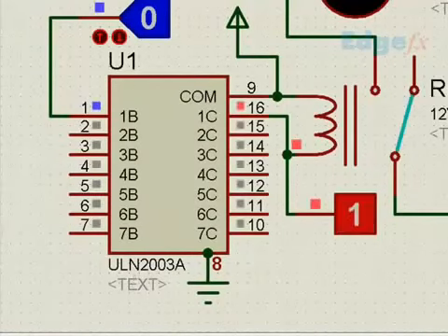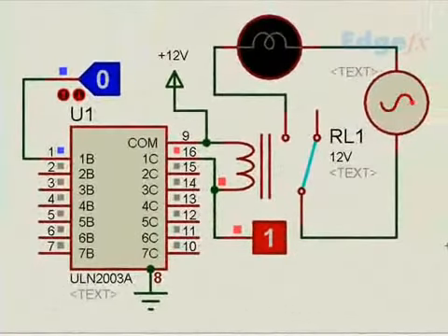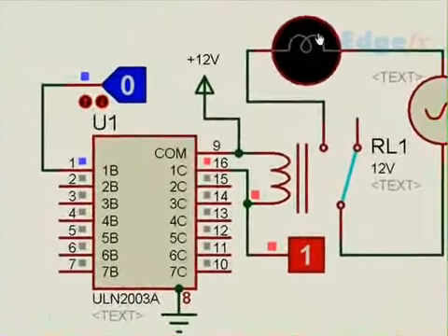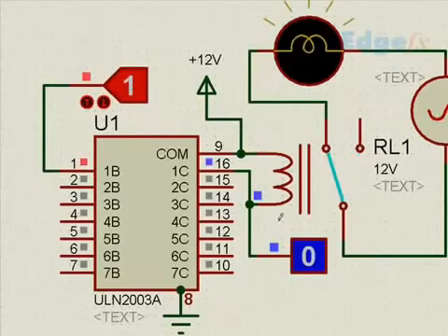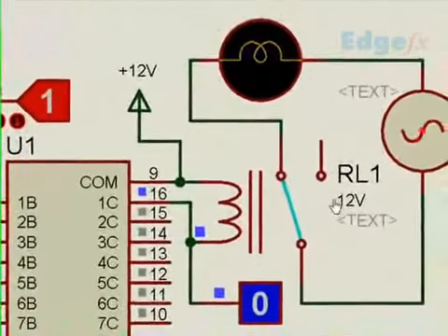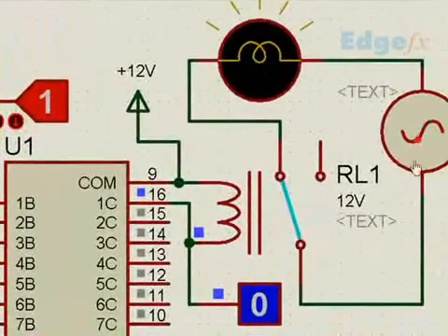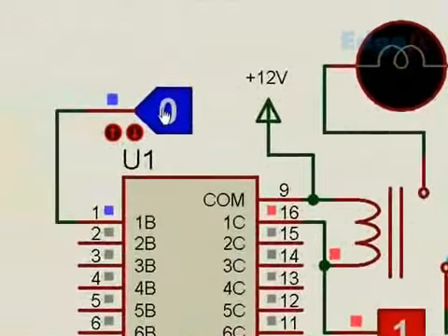Now when we operate this particular system, we find the AC supply is available and this lamp is not glowing. Why? Because this point is high and this point is also high, high being 12 volt, and this point we find in logic is also high. So high to high, the current is not going to flow. Once we make the input high, this goes to 0 and this point changes to this side and the lamp starts glowing. And if I make it 0, the lamp stops.